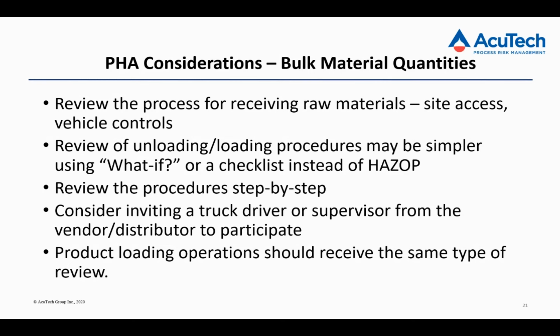Review your unloading procedures step by step. You might have steps out of order. You might have steps that are missing. I once was doing an unloading PHA, and just a simple step like chocking the wheels of the tank truck was omitted from this one procedure.